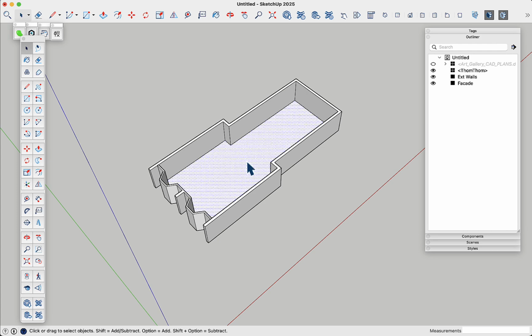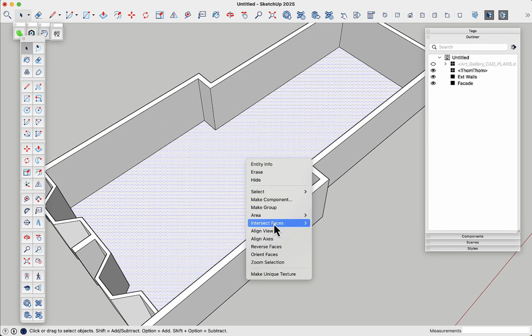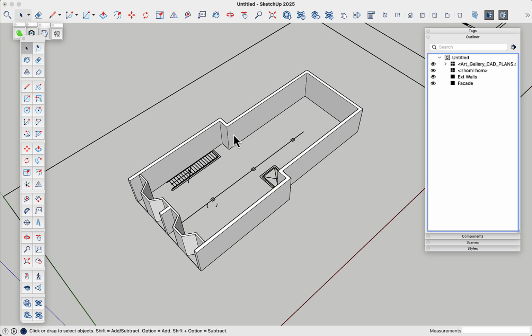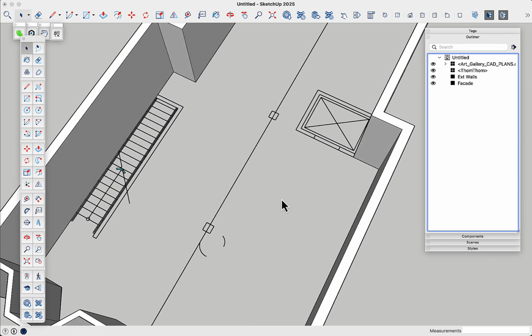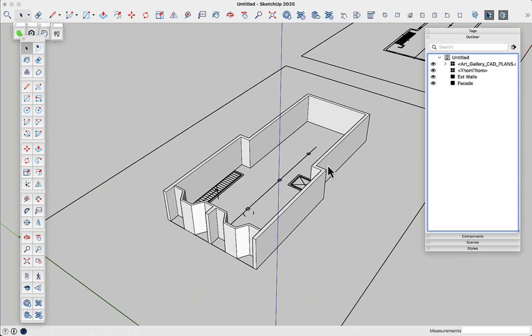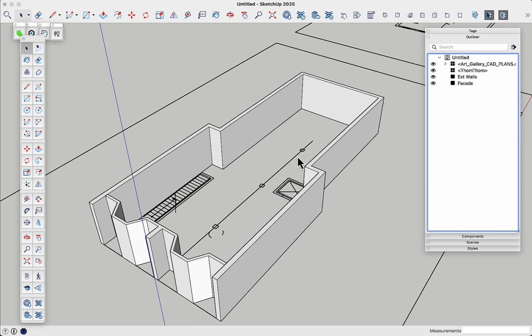If your CAD plan had, let's hide this face, or turn the CAD plan back on. And now I can see through it to model the elevator, the stairs, the columns, or any other interior walls that you may have brought in with a more finished plan. So I hope that helps. Bringing in AutoCAD plans is very useful in SketchUp since you've already taken the time with the precision, scale drawing, and that they come in without needing to be resized.